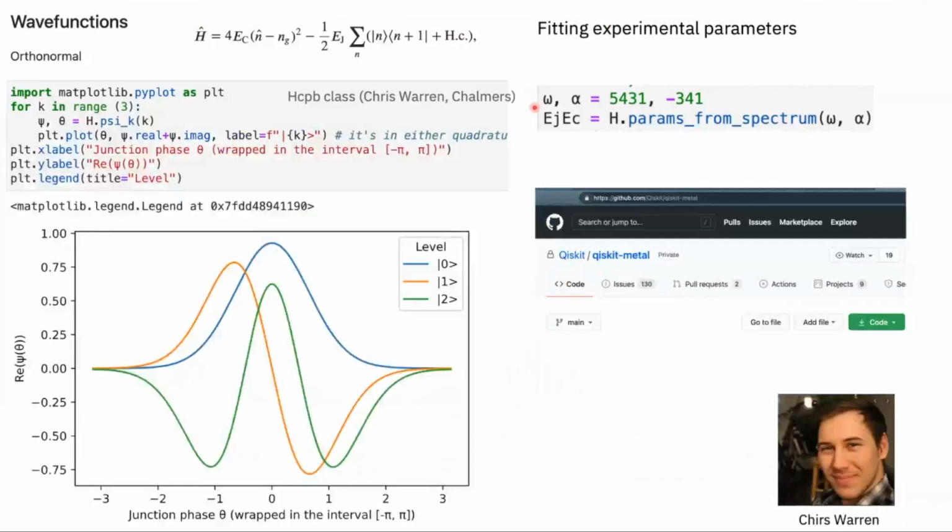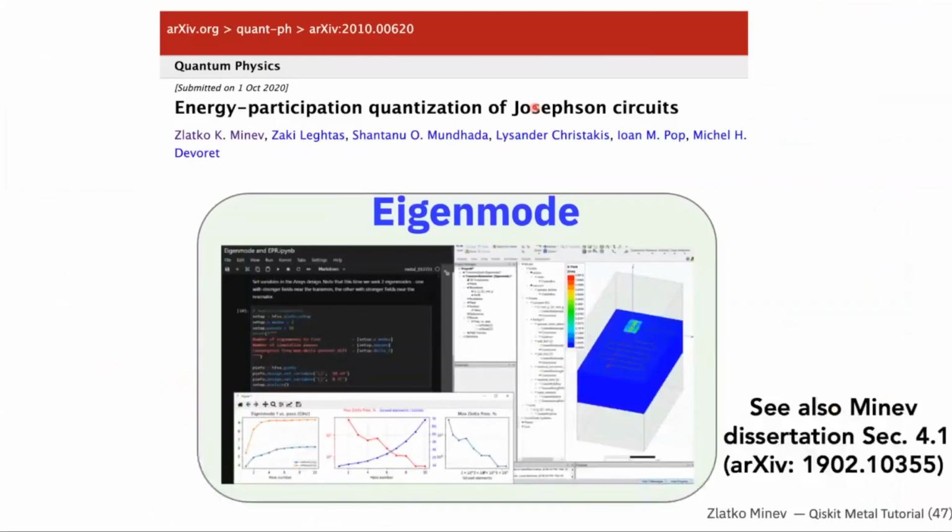And so this is perhaps the simplest way you could treat things, is with this capacitive approach where you extract parameters. Now, if you want a more correct approach, even though the capacitive can work really well if you have planar structures, if you have three-dimensional 3D structures, cavities, or you want to really get at the details of things and get things very precisely, then you can apply the eigenmode approach, which doesn't take this approximation that things are capacitors or inductors. It just simulates Maxwell's equations to their full glory and beauty. And so for details on the physics of that, take a look at this paper. Here, I'll just give you the big picture.